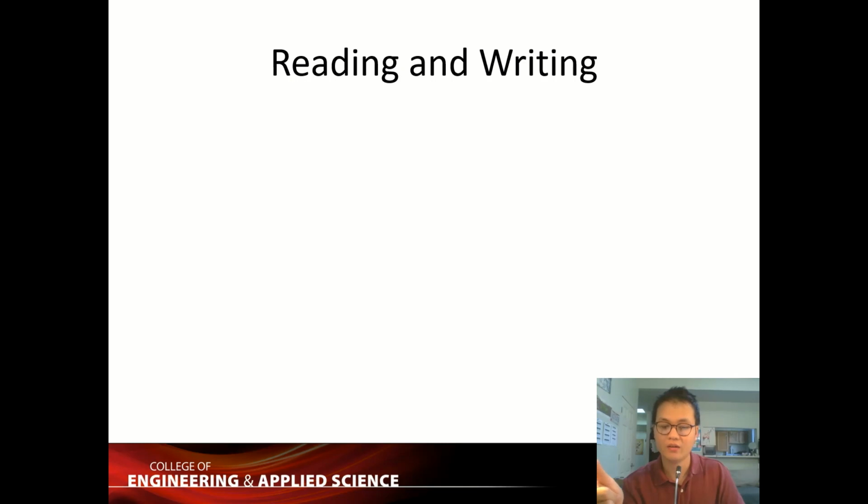So read and write: first step, address. Second step, depending on read or write, if you write you have to apply an input. If you read, you can skip the second step. And the last step is to activate either the read input or the write input.